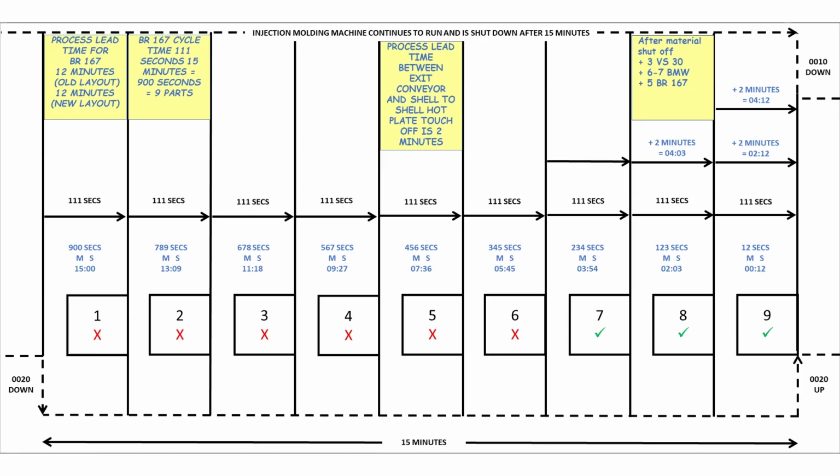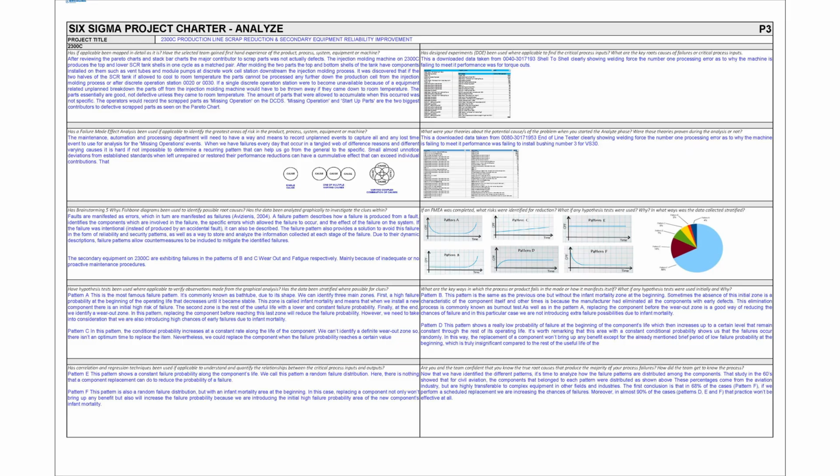This is my calculation that shows the logic that it's better to shut down the injection molding machine at each breakdown because we scrap more parts by continuing to run the machine. Shutting it down would be better. This is based on the amount of startup parts that were automatically rejected during a startup procedure over the number of parts scrapped over a 15-minute period for the same time.